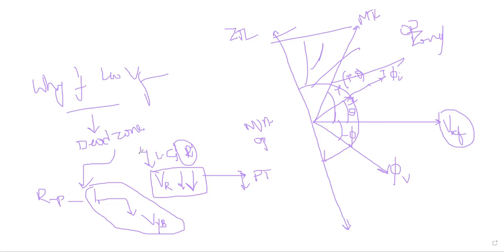Again, in the directional overcurrent protection, one more important point is that this is the case generally for phase faults. Then what about the directional earth fault relay, 67N? We talked about the 67. What about the 67N, and what is the non-directional overcurrent relay, 51N? We have seen the settings, but in the earth fault we always have two methods. One is the measured earthing system. The other one is the direct or derived earthing system.